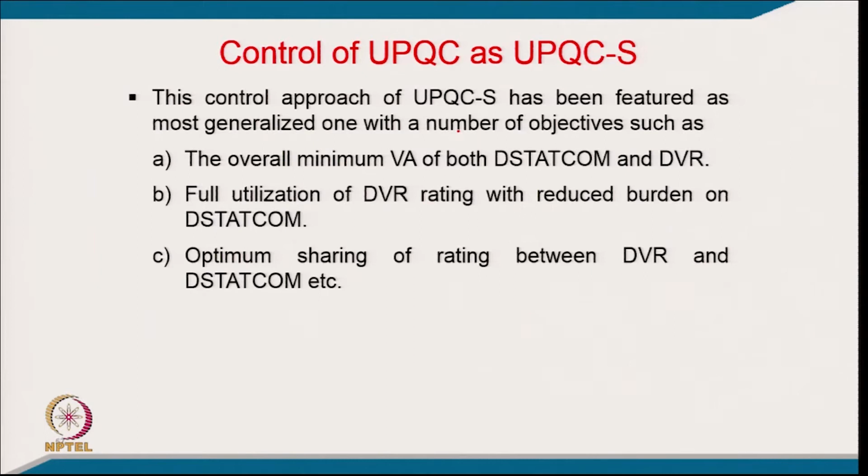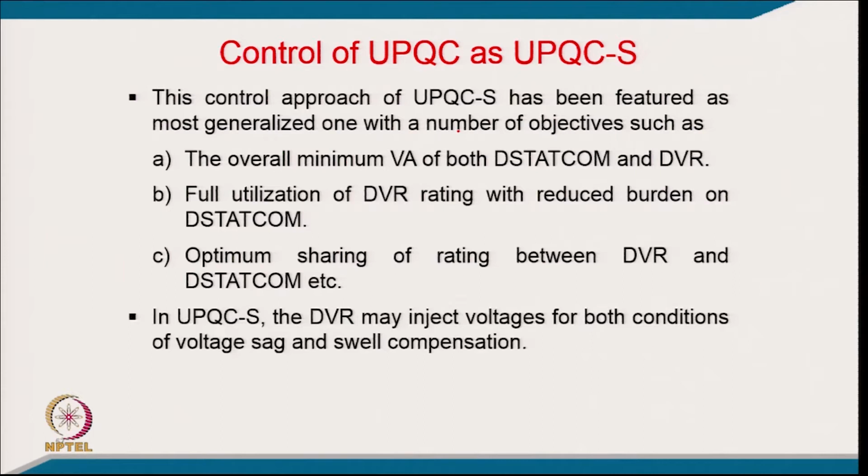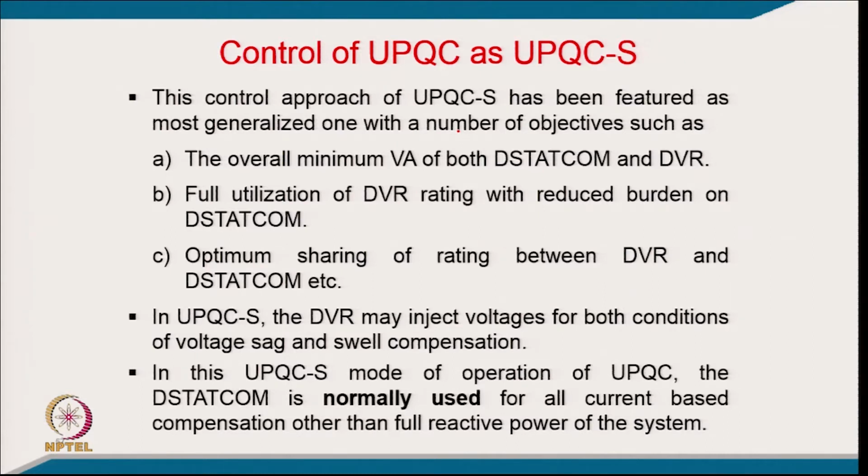So, coming to the control of UPQC as UPQC-S, the control approach of UPQC-S has been featured as the most generalized one with a number of objectives: the overall VA rating of both D STATCOM and DVR, overall minimum rating, which consists of the rating of DVR and D STATCOM, utilization of DVR rating with reduced burden on D STATCOM, and optimum sharing of rating between the DVR and D STATCOM. So, in UPQC the DVR may inject the voltage in both conditions of voltage sag and swell, and in this UPQC-S mode of operation of UPQC, the D STATCOM is normally used for all current based compensation other than full reactive power of the system.